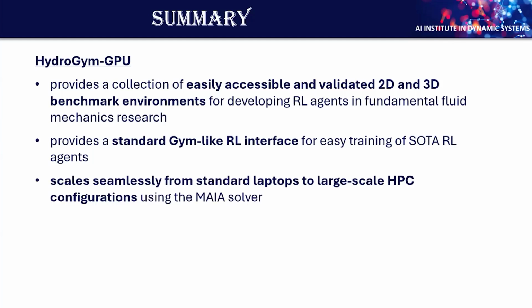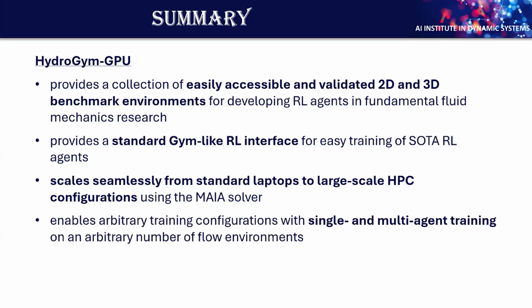We also ensured that we can use Hydrogym-GPU directly for the small test cases on a standard laptop, so I can train it on my own notebook, which requires something like an hour. But it is also well suited for HPC clusters, which in the end will drive our main applications in the future, more challenging 3D applications containing millions of cells. Moreover, we developed a new MPI interface, which is based on MPMD, to enable a direct communication between the agent and the flow environment, which makes it super fast. Therefore, we can also directly switch between single and multi-agents with barely changing anything in the code.